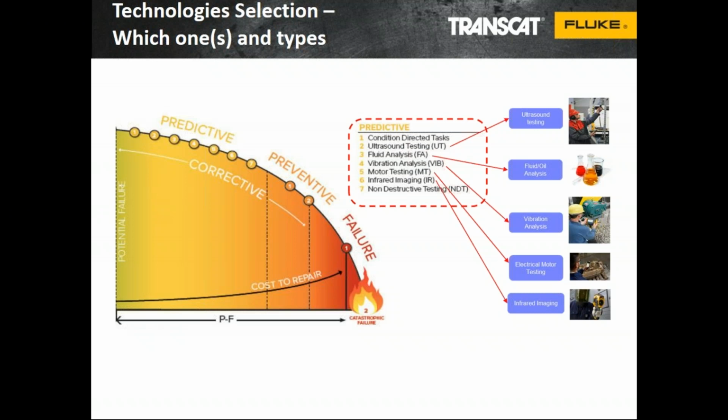What's interesting is that on the preventative side we see 1 and 2, and on the failure side, the bottom line is we don't want to catch things way down this curve before it's too late. Let's say we're looking at the temperature of a motor, using thermography or maybe just a contact sensor. If the motor temperature gets too hot around the bearing, in many cases it's too late, because the friction from that bearing has already worn it, and we already see there's a problem. But the bearing could have been changed, or some action done, before that.